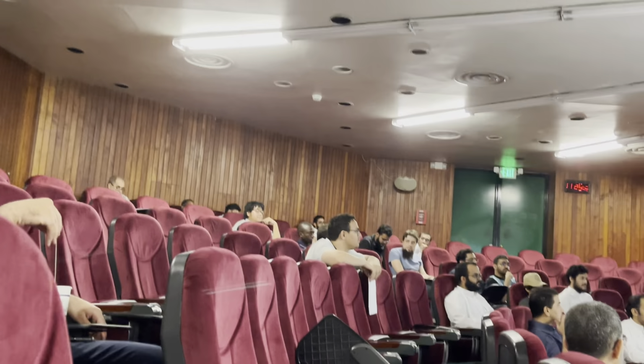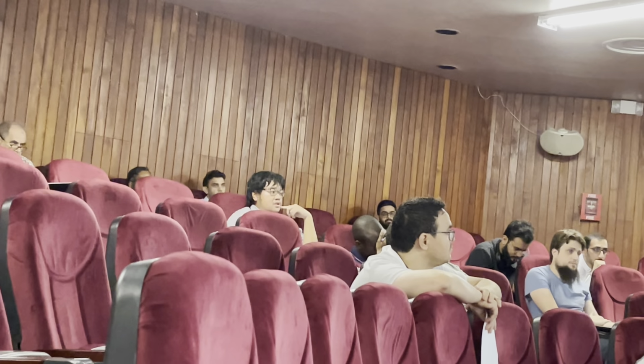Go ahead. Yeah, so your question. Let me just ask a conceptual question on that. At the beginning, you mentioned that with superconducting circuits, you normally don't want to encode your qubit in a harmonic oscillator, but rather in a circuit comprising a capacitor and a Josephson junction. That is usually called a transmon. There are also other types like the fluxonium, SQUID, and so on. But can you tell us, because you haven't really covered this in your presentation, what the differences are between all these different circuit realizations, and maybe the advantages and disadvantages.